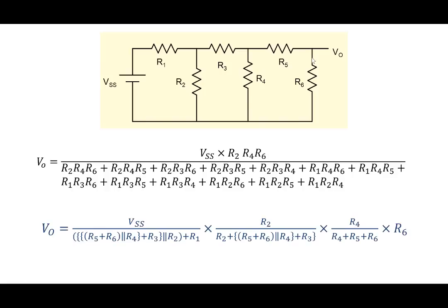All right, so let's compare the two expressions. We have an expression like this here that we obtained, let's say, through the mesh analysis. And we have an expression here that we obtained using our reuse methodology, using series, parallel resistors and current division principles. Now, of course, you can take this expression and factor it and get this one here in principle, but it's not going to be easy.